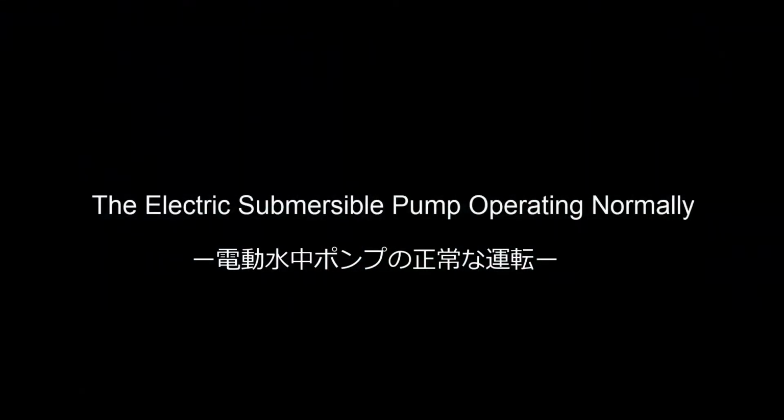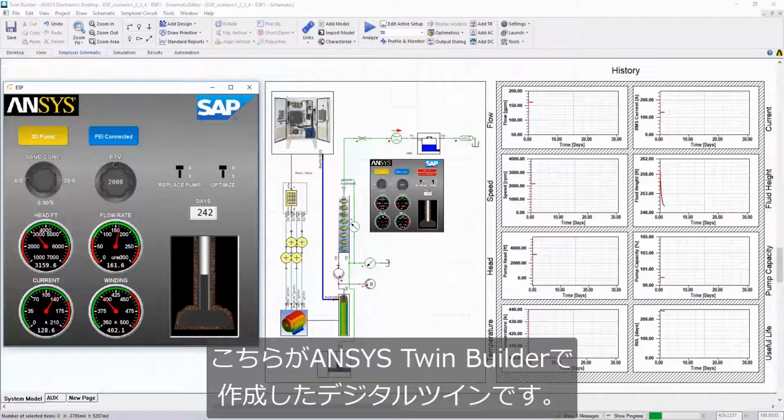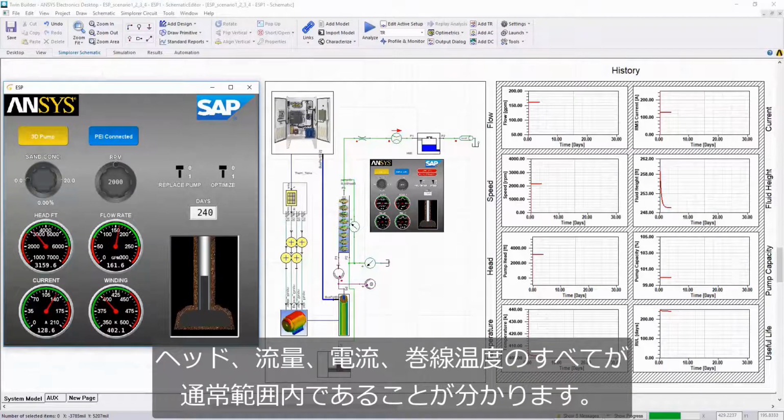Let's take a look at the digital twin of the ESP. Here's the twin created with Ansys Twin Builder. We can see that the head, flow rate, current, and winding are all within normal range.